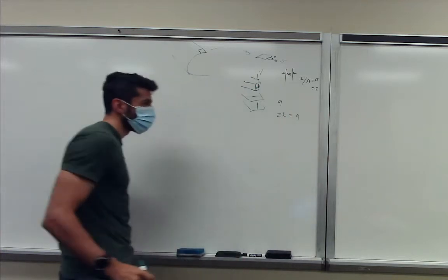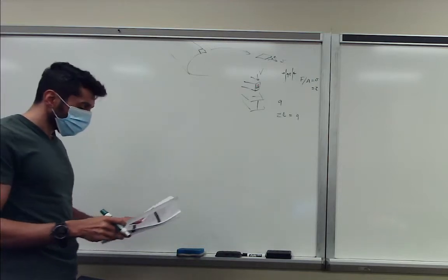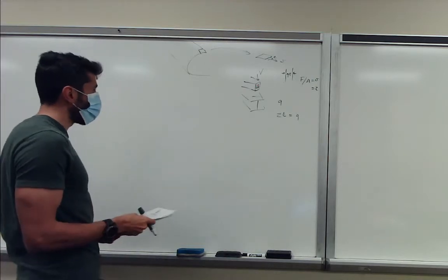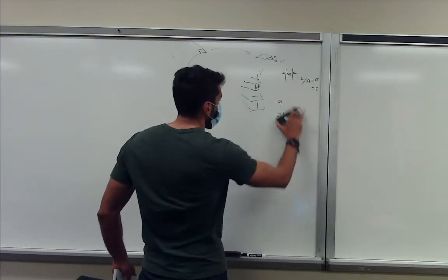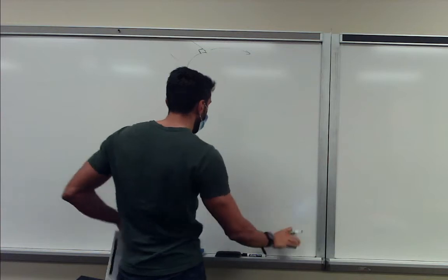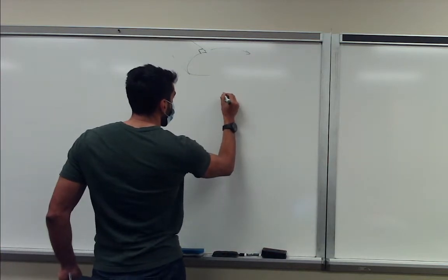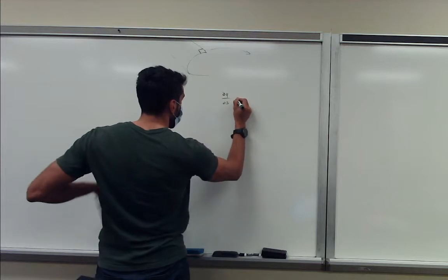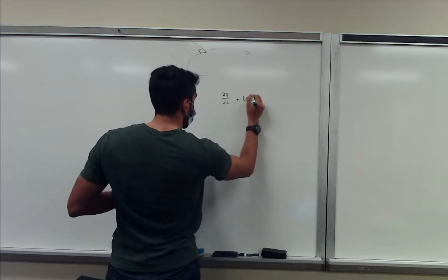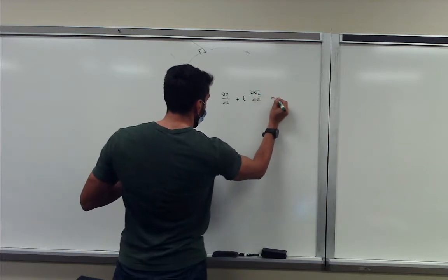So that's where we start. Now we did the equilibrium equations, and from the equilibrium equations we realized the following: dq/ds plus t dσz/dz is equal to 0.